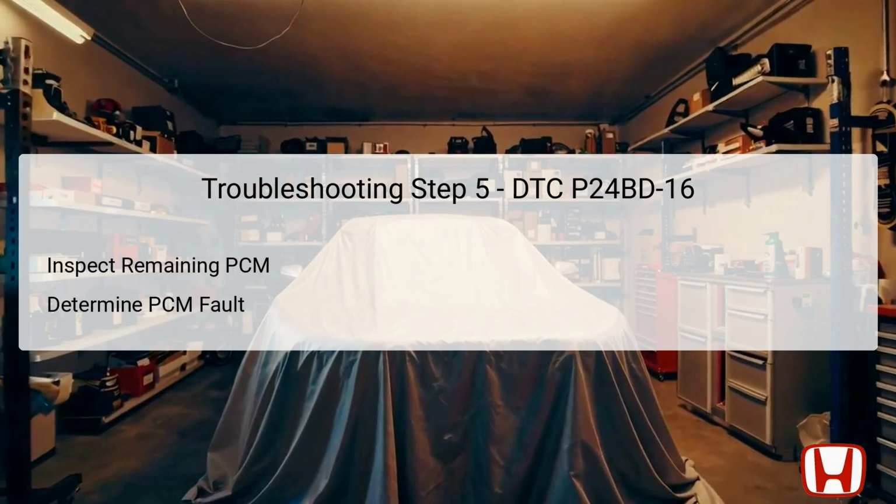Additionally, utilize HDS to perform any further diagnostic checks specific to the PCM functionality. Should these inspections confirm an abnormality in the PCM's operations, it is warranted to proceed with replacing the faulty unit. This step ultimately ensures that the PCM is not the source of the canister change over valve circuit low voltage error, which improves overall vehicle performance and emissions compliance.